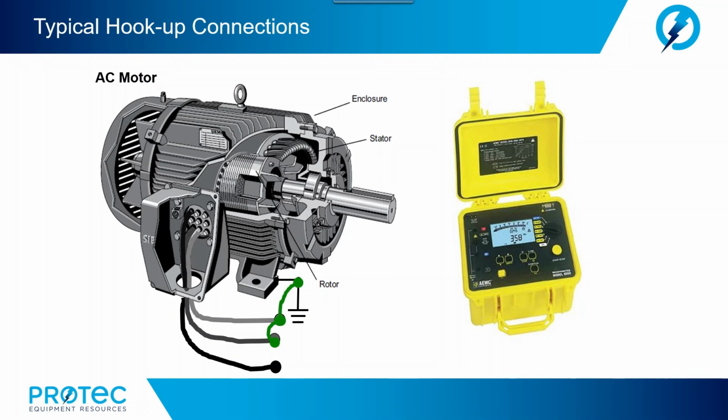And as far as our connections are now concerned, we ground the conductors, as mentioned, that are not part of the test, and we ground them to the rotor or stator chassis. We connect the positive lead to the ground, the negative lead to the conductor or phase of interest, and perform our insulation resistance test. And then we would basically repeat this hookup for the other two remaining phases.